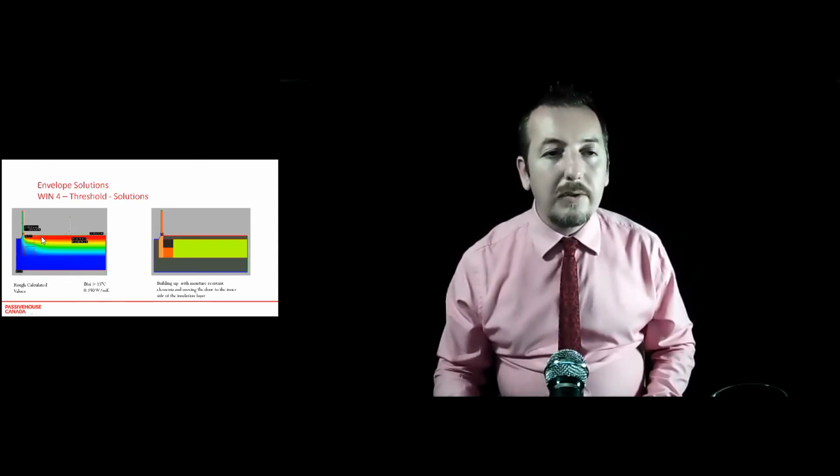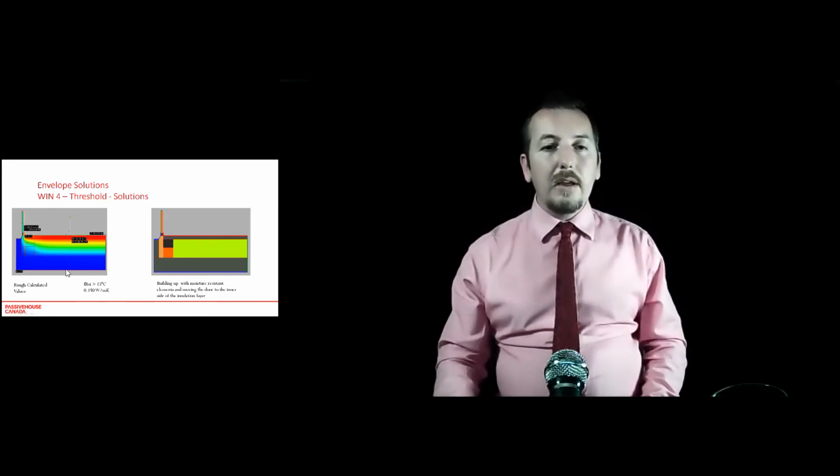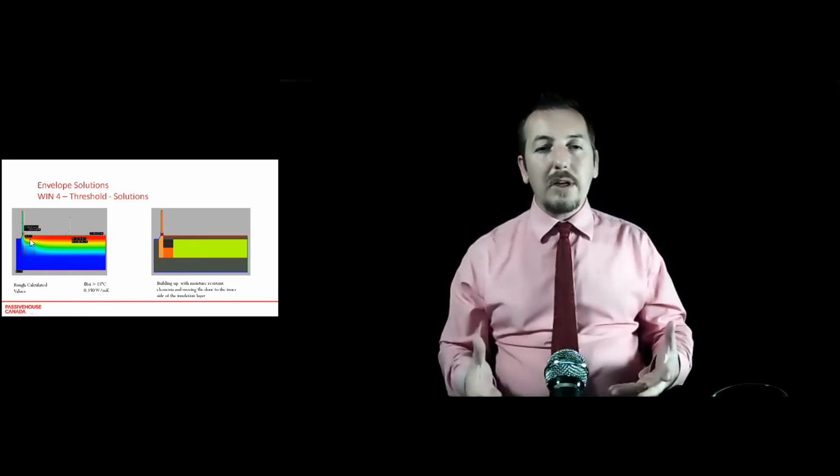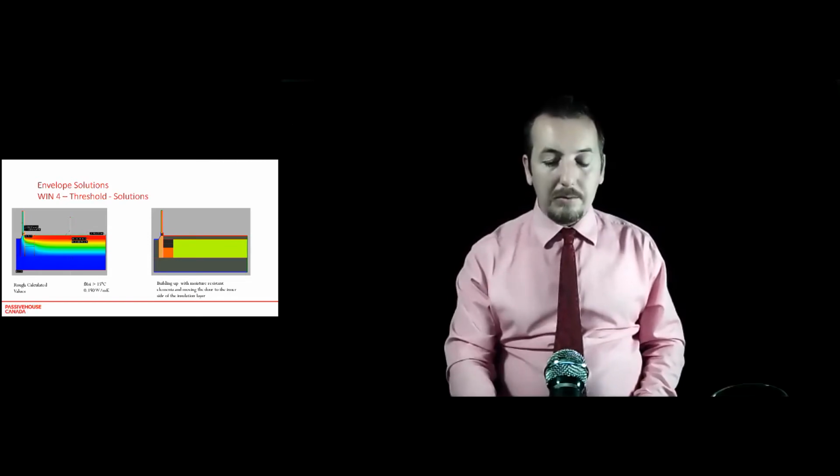We got the surface temperature to 15.78 degrees. Now, if you have a high psi value here, and really we should have 16.5 for comfort, but if you have a high psi value here and you've achieved a surface temperature, for a threshold, if it's just one small front door, it's not going to be the worst thing.